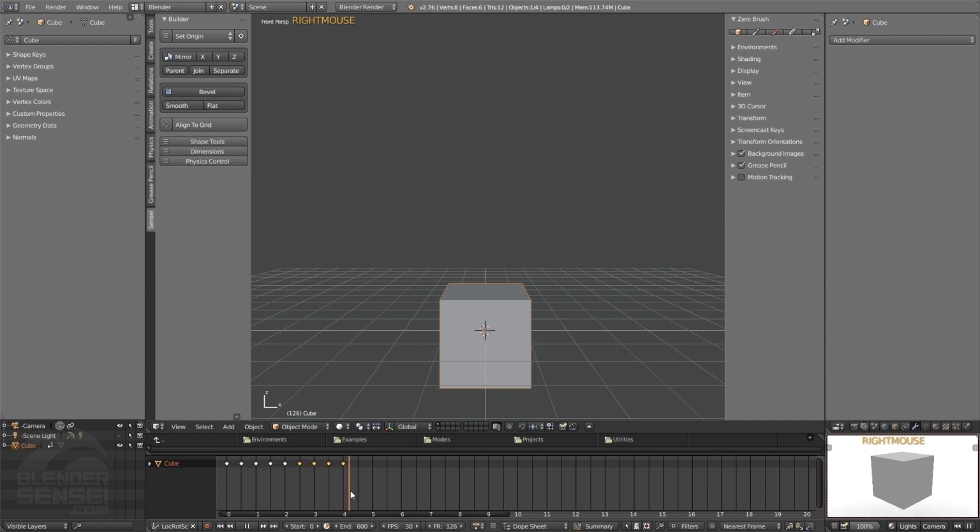Maybe only want to render a half second to a second past your actual last animation frame, depending on your specific needs. If we drag that to 4.5 seconds, we'll see that's at frame 135. So what we would want to do is make sure that we set this value to the proper length so we're not rendering out a bunch of stuff we don't need to. So let's switch that total to 135 there.